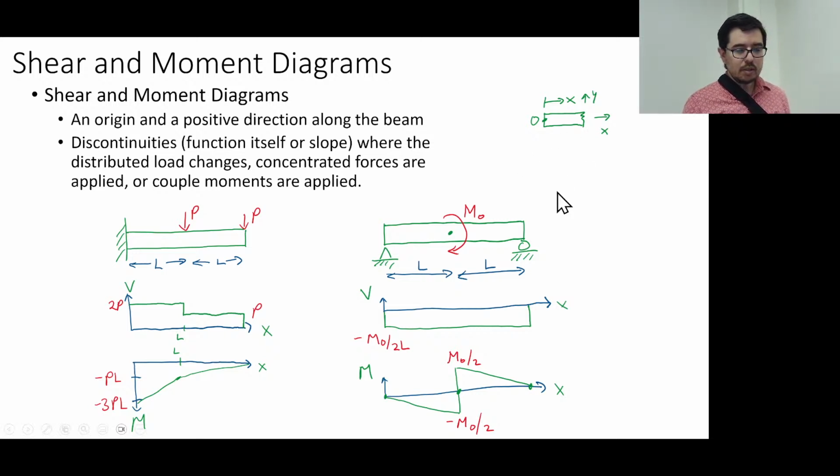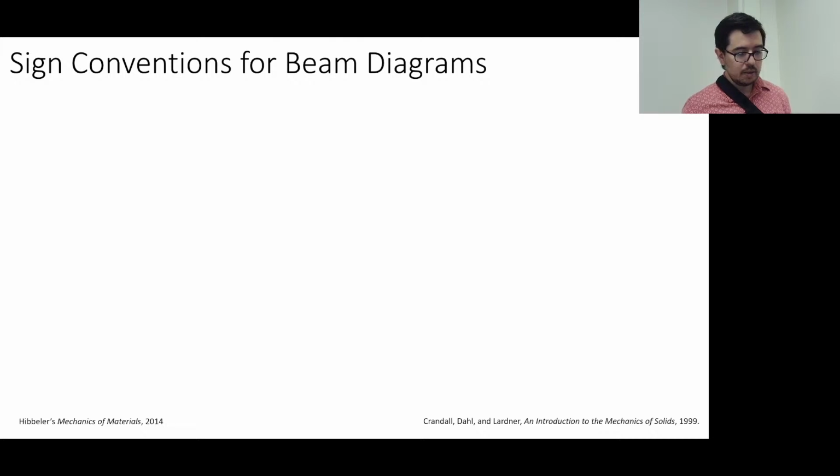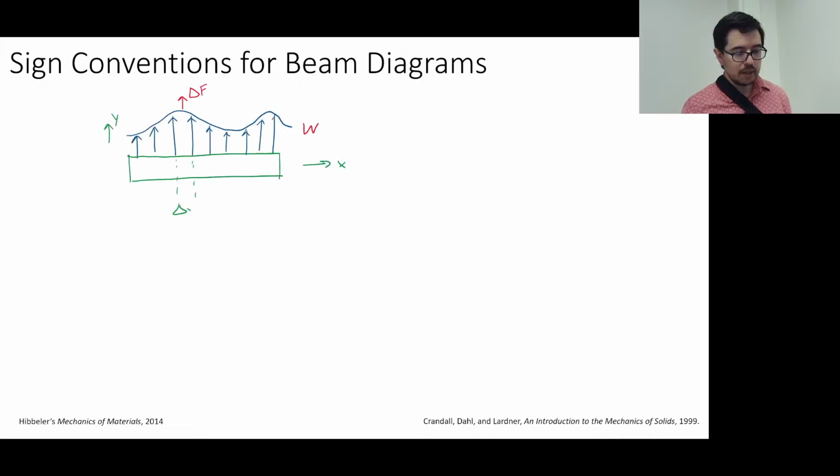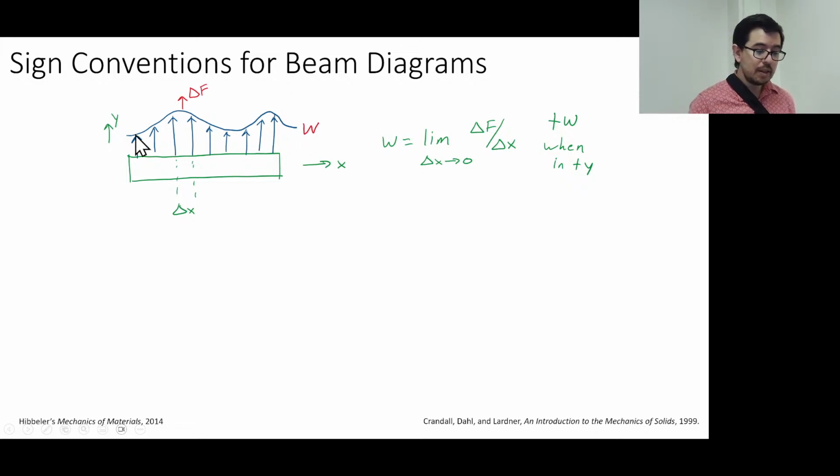You could do these, and we will do these, based on equilibrium, and we still use equilibrium on these sections, method of sections, quite a bit, and on external equilibrium. We've talked about the sign conventions a little bit, but here's another slide on that. With a distributed load, up is actually positive, even though a lot of the distributed loads are down. So those are negative.